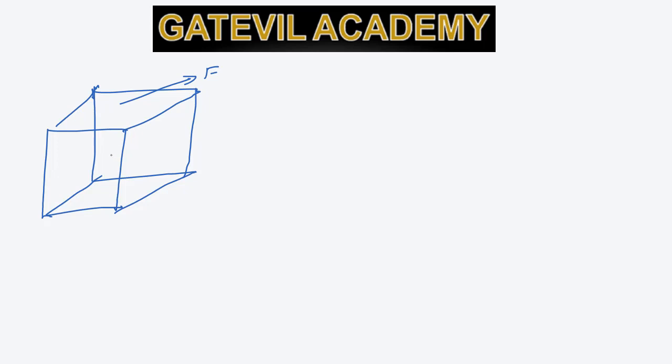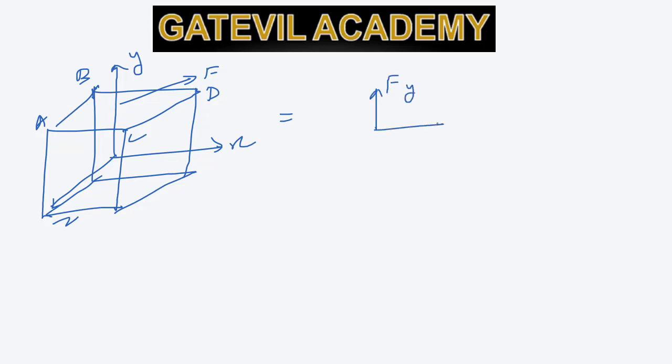Okay, so if this is X direction and this is Y direction and this is Z direction, on this plane ABCD, the internal reaction that is produced is F. It will have a component Fy in Y direction, Fx in X direction, and Fz in Z direction. These three components of the internal force F will produce three internal stresses: sigma X, sigma Y, sigma Z, acting upon the area ABCD.